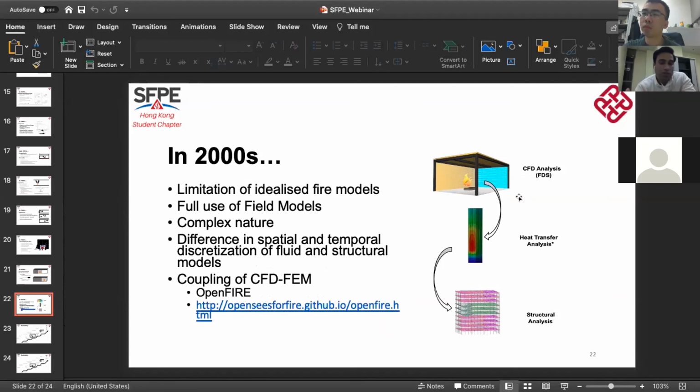If you are using wood cribs for simulations and want to validate the data, you have to make the grid size very small, which increases your computational time. Even with a 20-core computer, one simulation will take months, and after that the results might not represent reality completely. So this is quite a challenging part to validate. Wood cribs are less than 5 centimeters, so your grid should be smaller than 5 centimeters.